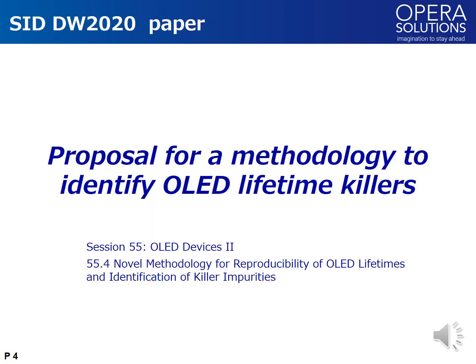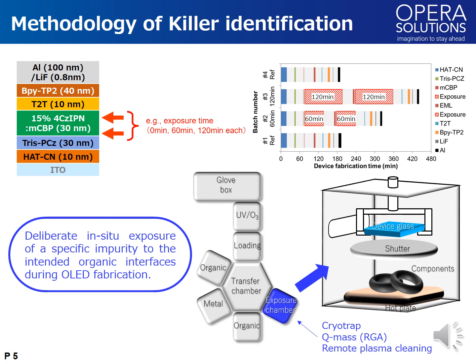Next, I would like to introduce a very unique method. You can find the full technical presentation at session 55 of the symposium, so I will show you here only a few slides for a brief introduction. Here I explain the concept. We attached a new customized chamber to the VT system. The aim is to perform intentional in situ impurity exposure to specific organic interfaces during an OLED fabrication.